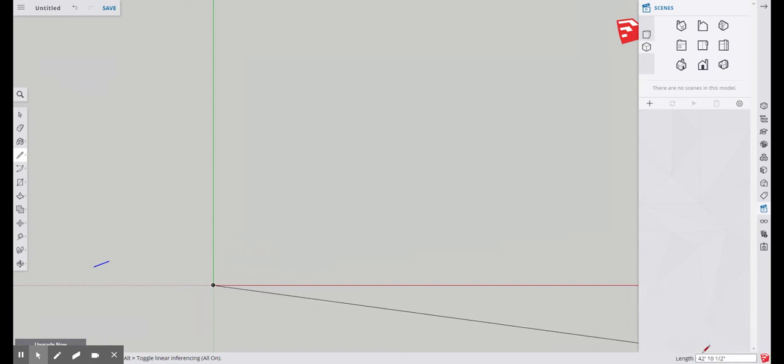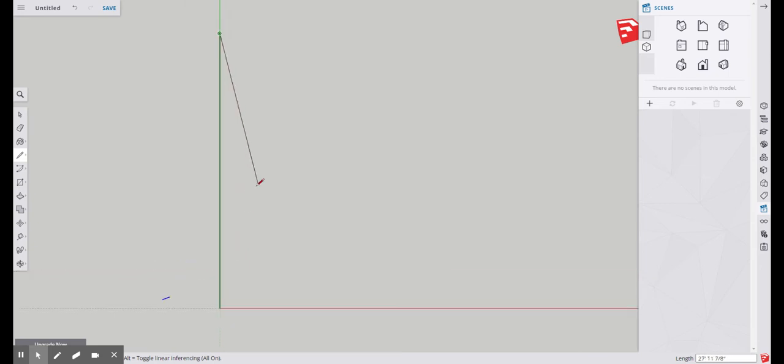Here now you can see it, it shows you the length. I'm going to click 50 feet. And our feet is just the one little tick, and I'm going to click enter. Okay, I have not clicked anything on my mouse, and it took me to 50 feet.